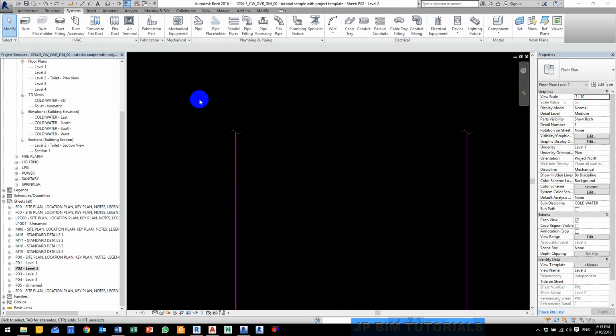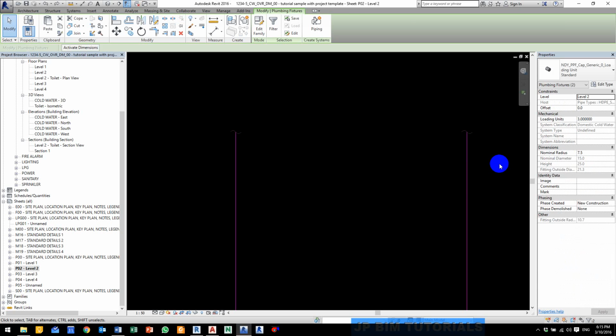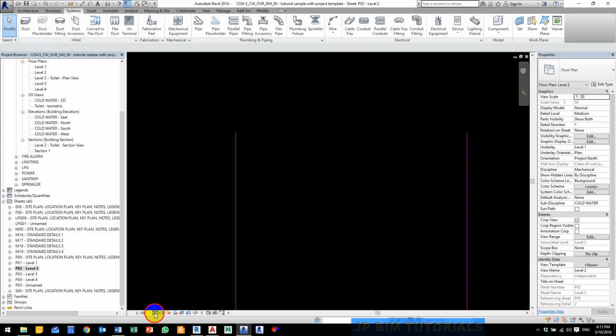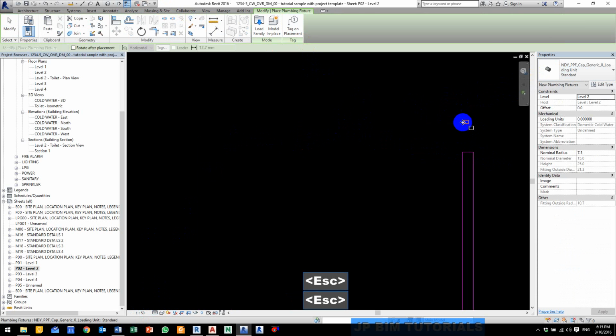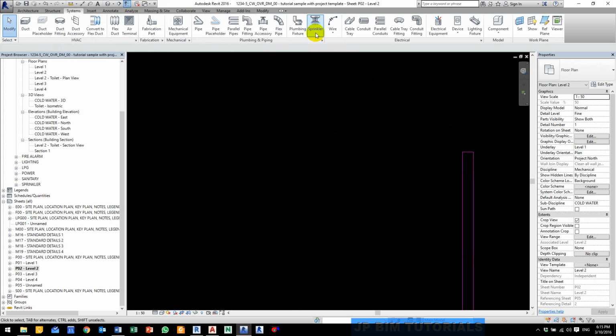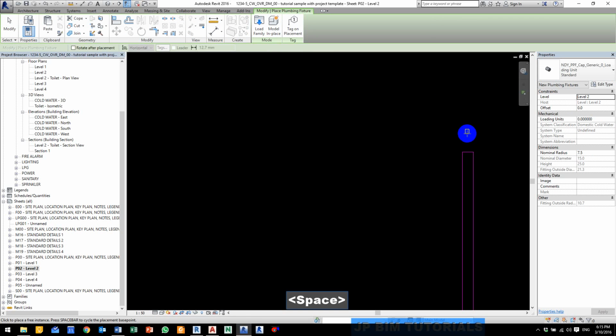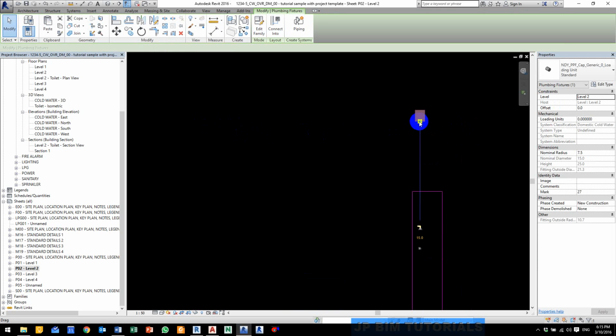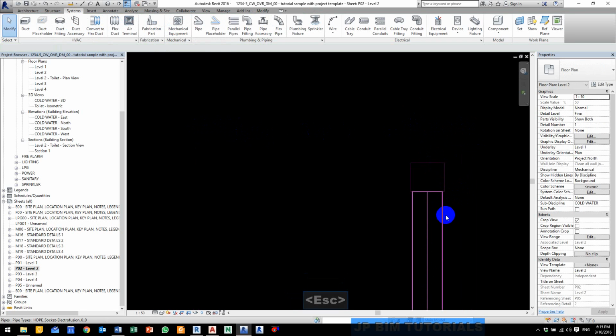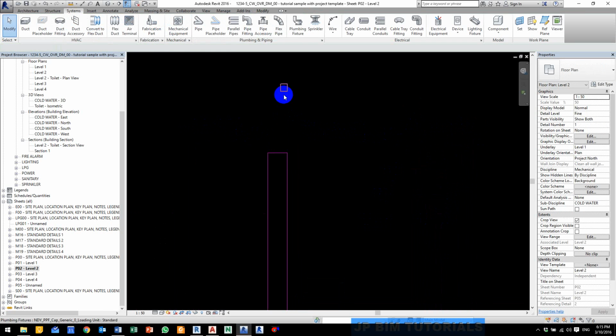Sorry, let's just restart that. I'm just going to delete these 2 caps again, change this to fine detail, reinsert the caps, just put one here first, delete, rotate it accordingly, just put one cap here and one cap here, escape, select the cap, drag the connector to this pipe to ensure that it's actually connecting to the pipe. Same thing with this side.